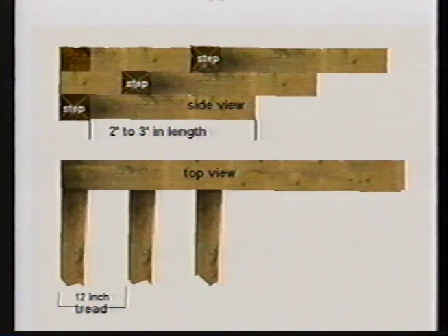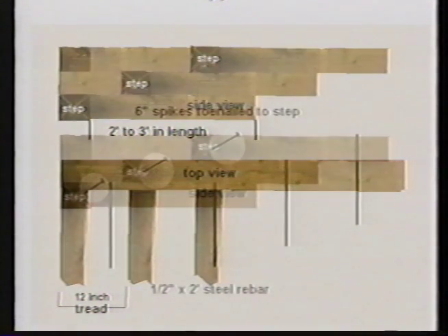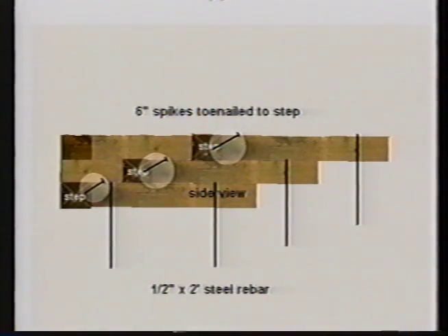We recommend that the tread be 12 inches. Use your base course as your first step. Abut 2 2-foot timbers to the back of the base course to begin the step. Ensure that they are perpendicular to the base course with an inside separation of 3 feet.